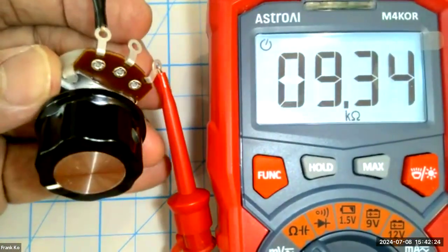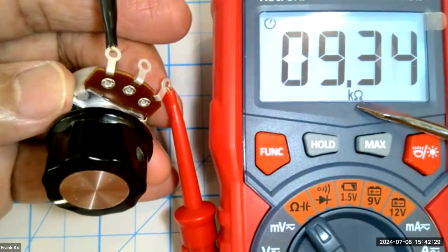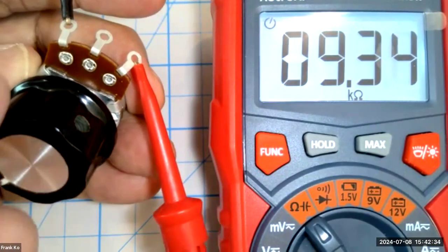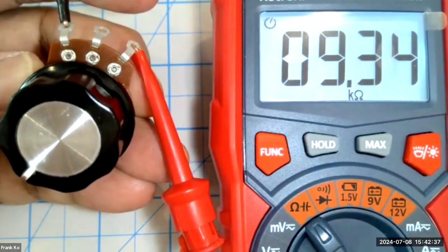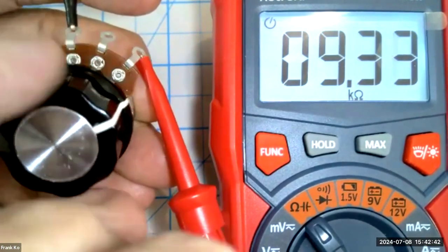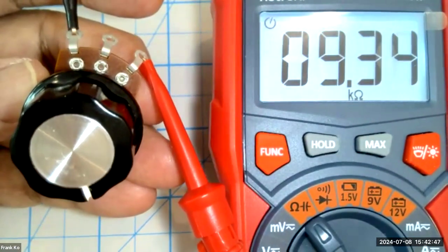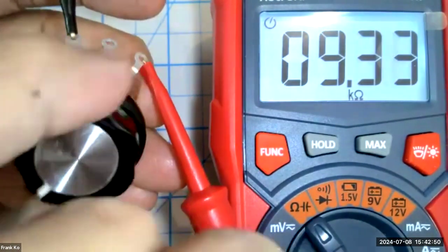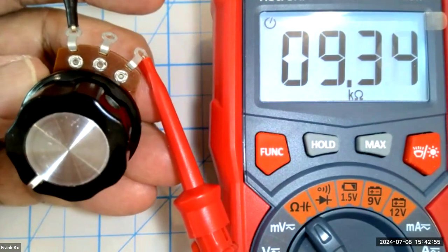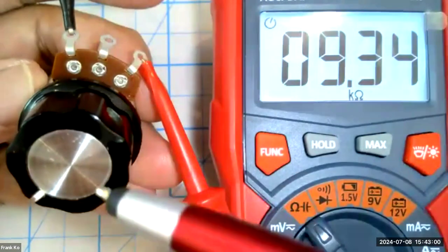Okay, all right. The multimeter is set on reading resistance, as you see, and I'm showing a scale of 2 kilo ohms, 9.34 shows here, and I have the knob all the way over, in this case, on the left. So as I rotate this clockwise from one extreme to the other, this is my 9.34, and rotate from one extreme to the other. Let it stabilize for a moment, 9.34. So what this goes to prove is the outside pins are not affected by the position of the knob.